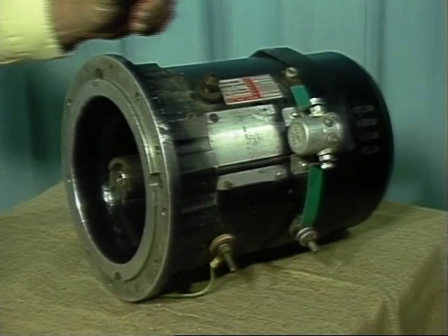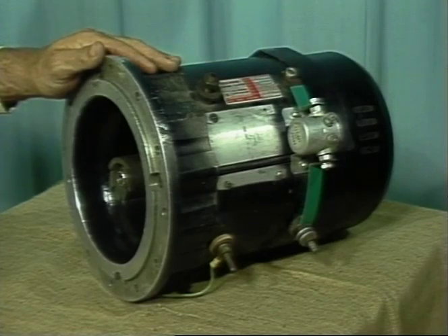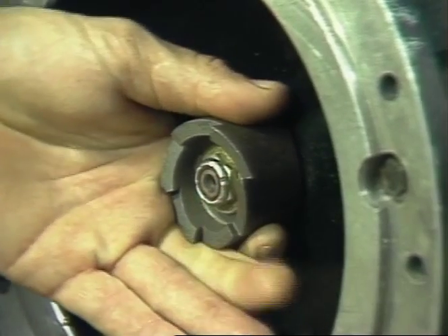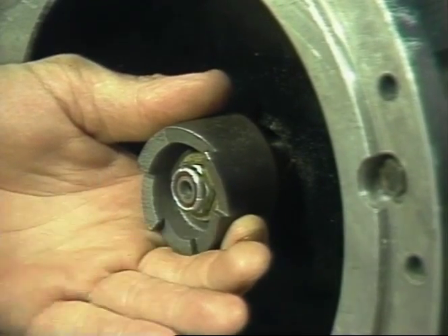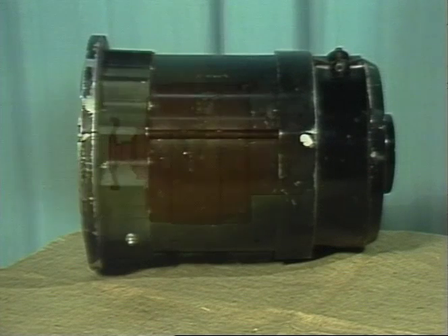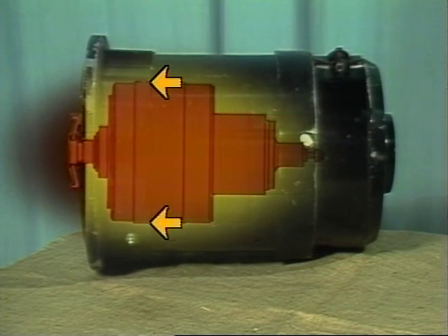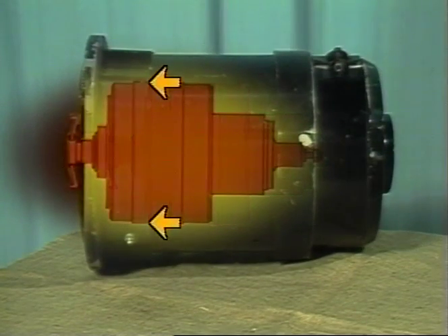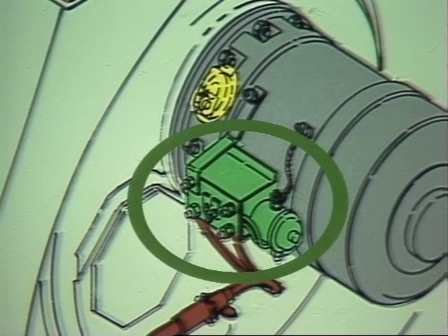The starter motor itself is a series-wound 800-amp 24-volt DC motor. As mentioned earlier, the motor assembly has a retractable jaw clutch that must extend to engage the accessory drive adapter jaw. This engaging process is accomplished by generating a magnetic field inside the motor housing that slowly shuttles the motor's armature to engage the clutch assembly. This magnetic field is controlled by the start contactor located on the starter motor housing.